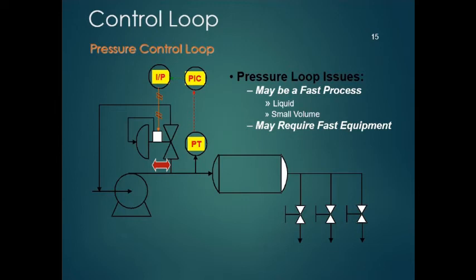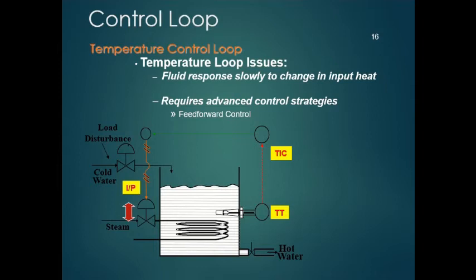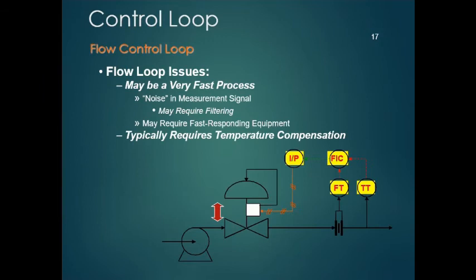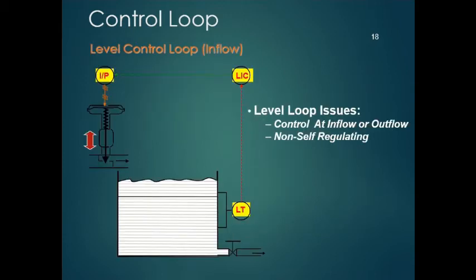The temperature controllers, flow controllers and level controllers are similar in nature in the control room, because they are converted from pressure, temperature, level or flow transmitters, and those 4 to 20 signals are evaluated and compared with the PV, that is process variable, and set point, and a final command of 4 to 20 milliamps or a digital signal is given to the final control element, that is a drive.